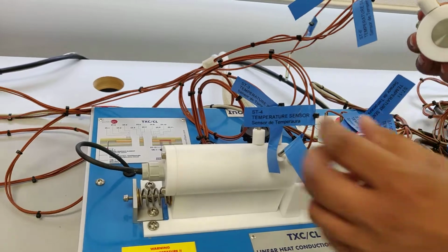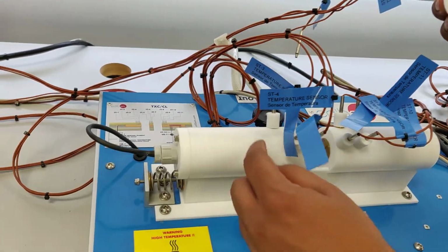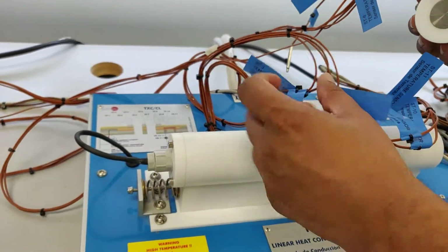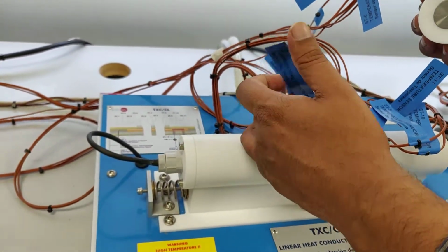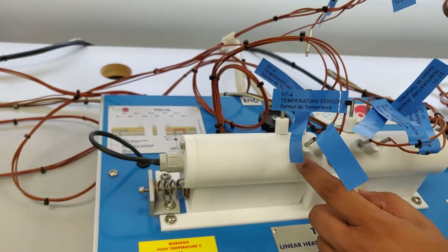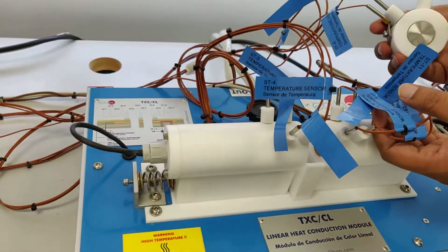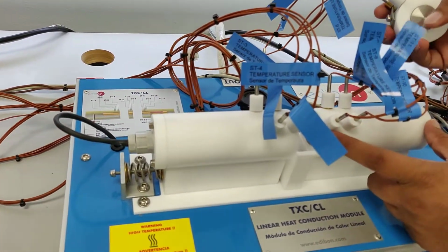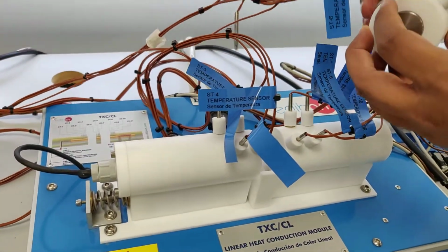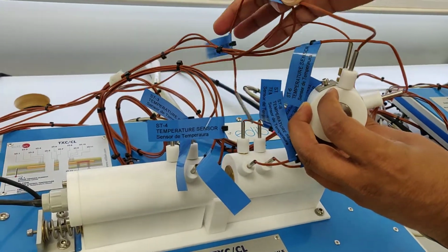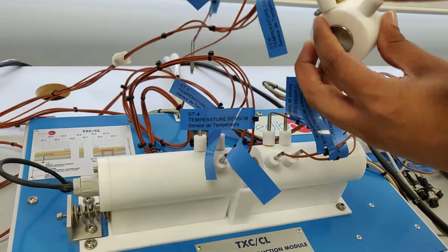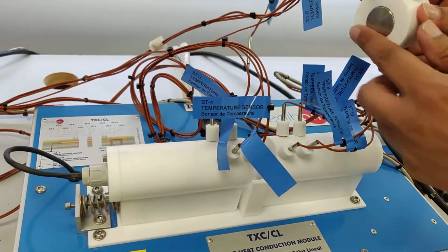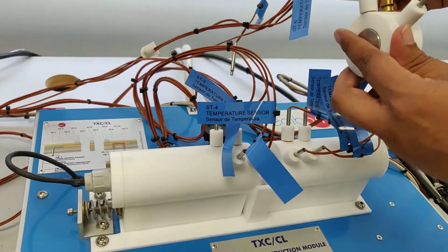Before that, we have thermocouple sensors 1, 2, 3, 4 with the numbers. This is T4, this is T2, and here this is T1, T3. So 1, 2, 3, 4 for the hot section, and for the cold section you have 8, 9, 10, 11, 4 sensors along the length. For the test specimen, we have the sensor numbers 6, 5, and 7. They are in order, 5, 6, and 7. So 5 will be on the left side and 7 will be on the right side.